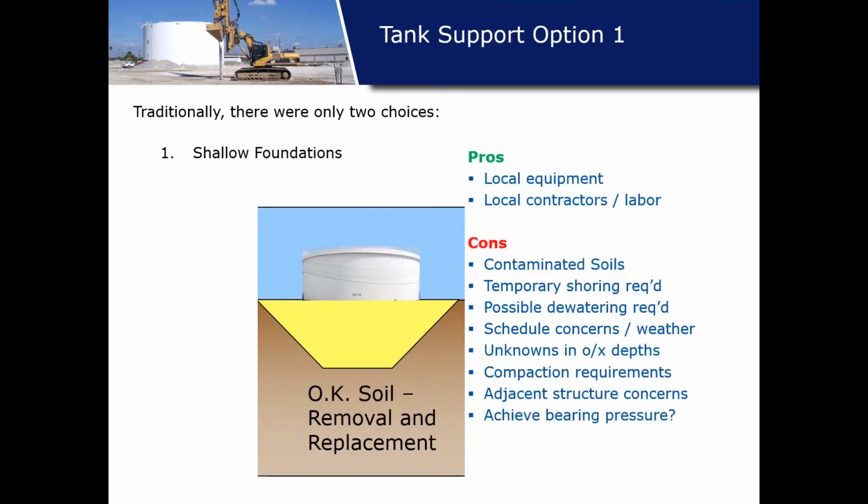Shallow foundations. Yes, you have local equipment and contractors available to basically over excavate the soft, wet, saturated, or undocumented fill and replace that with structural fill. But the question is, oftentimes the sites are contaminated, so you can't really over excavate easily as you would for a building.